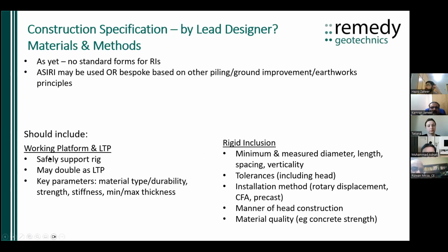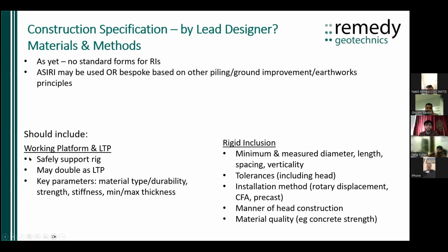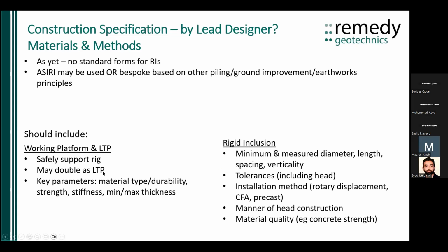And there are other things as well that you may need to consider. You may need a working platform to support the rig. Now that working platform may double, or may be reused, or considered as the load transfer platform, but the design needs to be specifying the material type and checking the durability, strength, stiffness, and variations in thickness of that load transfer platform. That all comes out of the design as well.